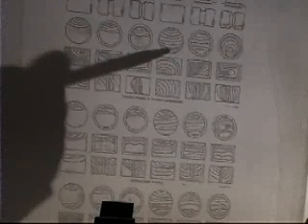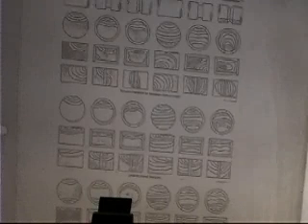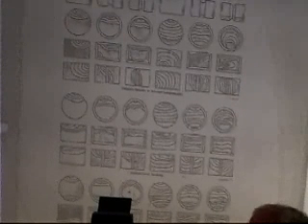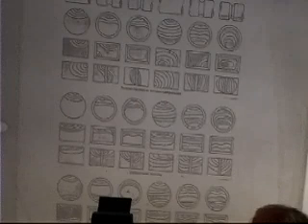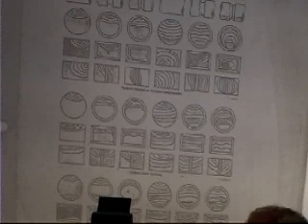I also told them there was no stress concentration, from the shape of it. And I told them this failure had occurred over a number of weeks, but not necessarily years, just by looking at the surface.